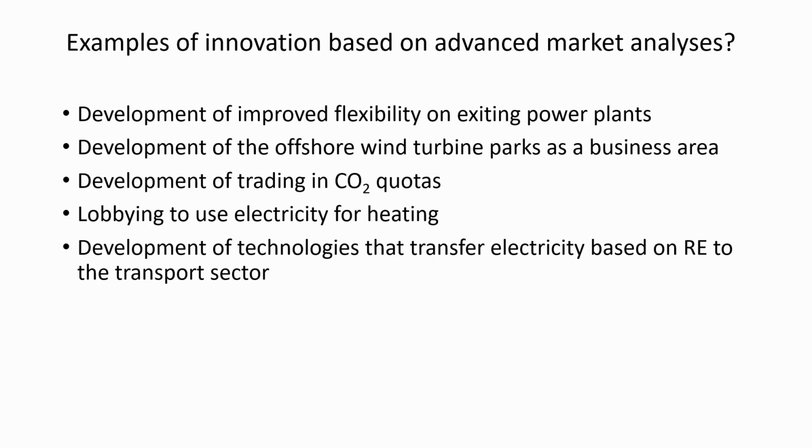Now I want to give you some examples of innovation that are based on advanced market analysis. At the beginning of the 90s, in the Danish electricity company Elsom, we did market analysis with an advanced market model. We inserted forecasts for expansion with wind power into the model and found that our existing power plants would have a whole new role in the electricity system. They would change from being baseload units to being intermediate and peak load units.